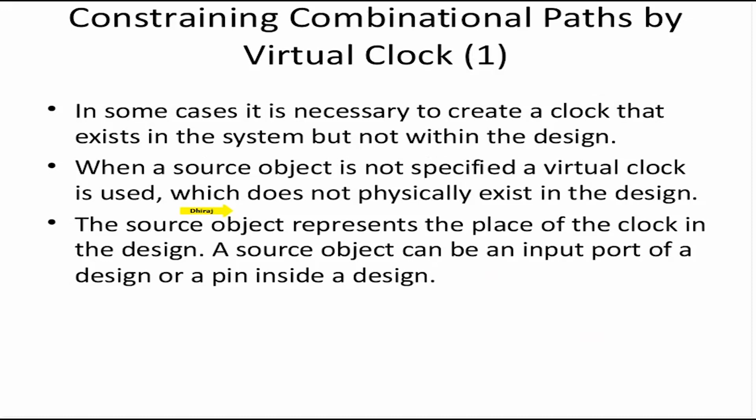Now, the create clock command needs the pin on which the clock should be defined. For example, the clock port of a design is called CLK. You say create clock minus period 10 nanoseconds, and you tell it what port to create the clock on, which is CLK.